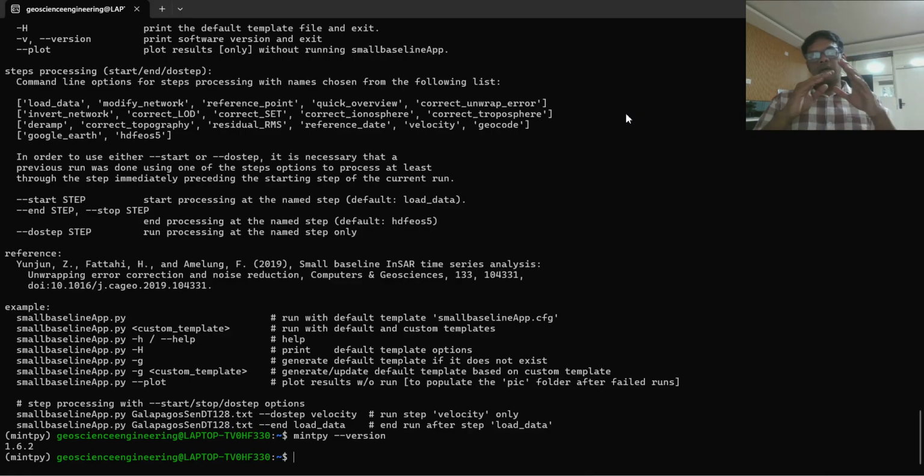When you go for a particular area study, you will take, like, 10 or 15 years of data. Whatever data you have, you keep everything frame by frame. That means, like every 12 days or every 1 month, you take the data and create a stack, and that stack starts with the interferograms. You keep all the interferograms together in a stack, and then we start the reconstruction of the deformation or the subsidence through time. That is why the interferogram stack is the first important thing.